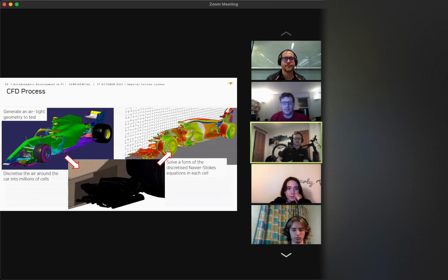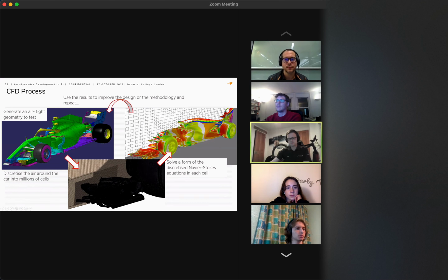Thank you. So this is the design process. You start off with having a great idea on how you can design your car. You design it in CAD. We typically only do half a car because it makes things more efficient. Once you've done that, we have to chop it into millions of little tiny cells. And then in each one of those cells, we solve a discretized version of the Navier-Stokes equations, which give us these beautiful, pretty pictures. So this is surface pressure over the car, along with total pressure along the slice. And we can use this information to go and design our car.